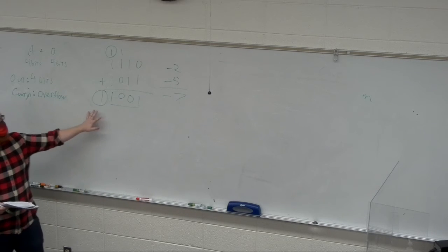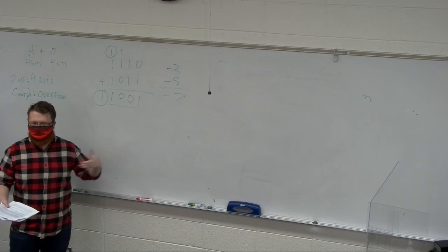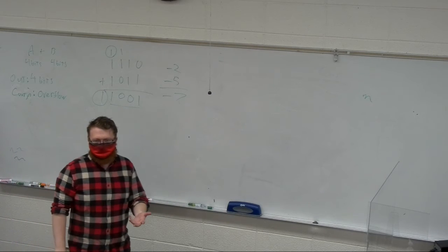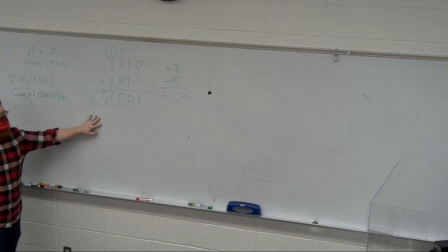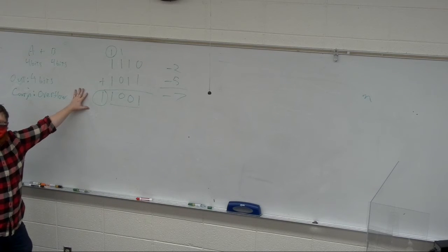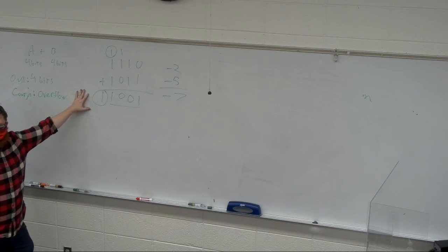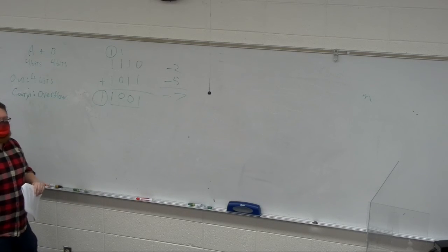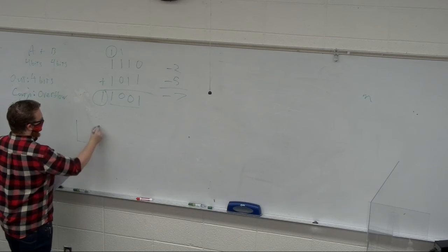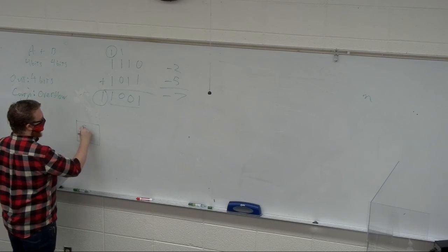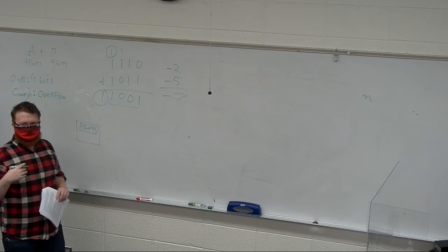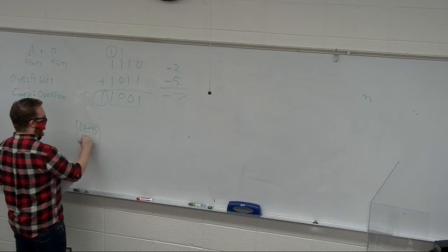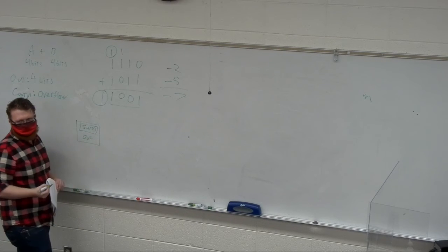And so we can tell that we need the same thing. We already have a ripple adder, and we're just going to build this up as a ripple adder. But instead of using the carry out for something, we're going to add one logical expression. There's only one thing. You're going to have a sum block, but instead of a carry out on the last one, you're going to have an overflow, OVF.